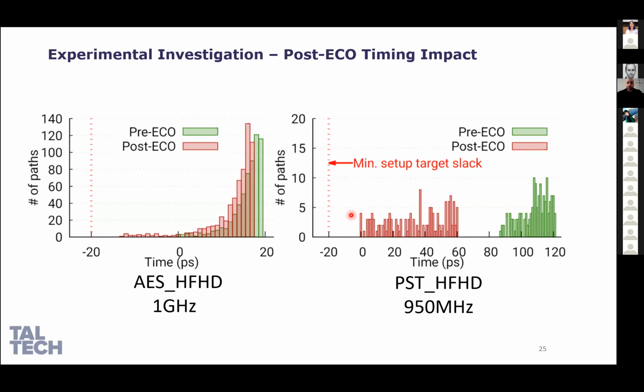And also we have to check the performance of the target after this hardware Trojan, even though we are not putting logic directly on the target. The routing wires and the extra filler cells that we are placing there introduce coupling capacitances, and they impact the performance of the target.